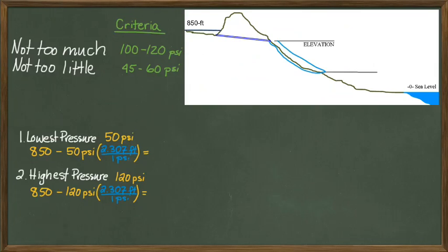The static head criteria is one of the main considerations when defining the service area of a water distribution system. These 2 elevations provide the city a hard limit for where new homes or shopping centers can be built, all by just quantifying the static energy of the water within the system.